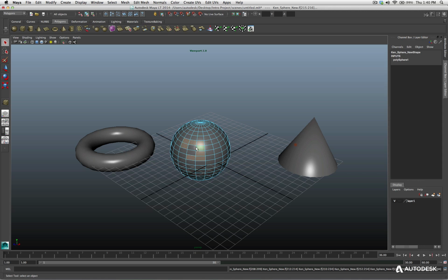But now what if I want to deselect these 2 faces right here? If I use the Shift key to deselect them and I accidentally touch some other faces, I'm going to be selecting them. And that's not what I wanted. I just wanted to deselect these 2. So let me hit Command Z to undo that. Now if I hold the Control key and I click and drag across those 2 faces, it doesn't matter if I accidentally include these unselected faces in my marquee. So that's really the benefit of using the Control and the Shift key as modifier keys when you're making your selections.